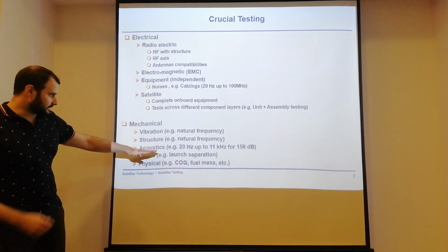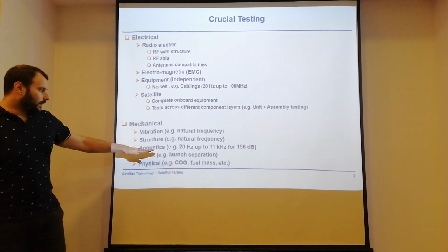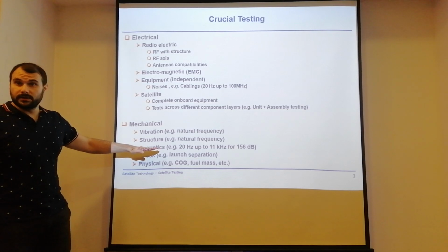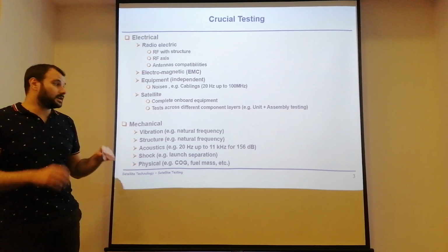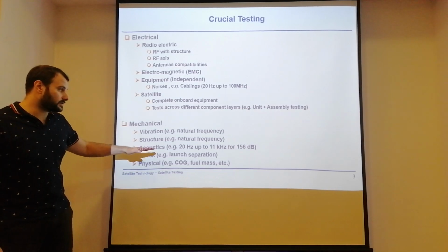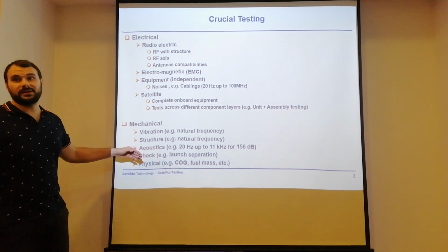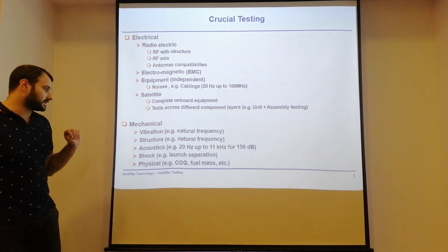You have acoustic tests because it is very loud during the rocket launch, also inside of the payload bay of your satellite bay. So you want to make sure that all those really loud noises don't damage the satellite. That's why you do acoustic testing.